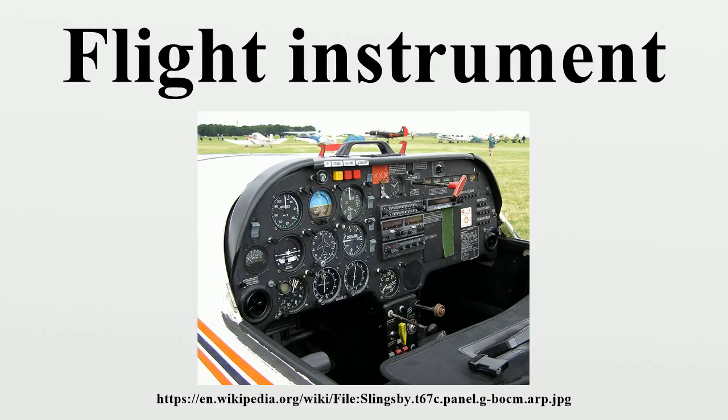With the advancement in aviation and increased altitude ceiling, the altimeter dial had to be altered for use both at higher and lower altitudes. Hence, when the needles were indicating lower altitudes, i.e., the first 360-degree operation of the pointers was delineated by the appearance of a small window with oblique lines warning the pilot that he/she is nearer to the ground. This modification was introduced in the early 60s after the recurrence of air accidents caused by confusion in the pilot's mind. At higher altitudes, the window will disappear.